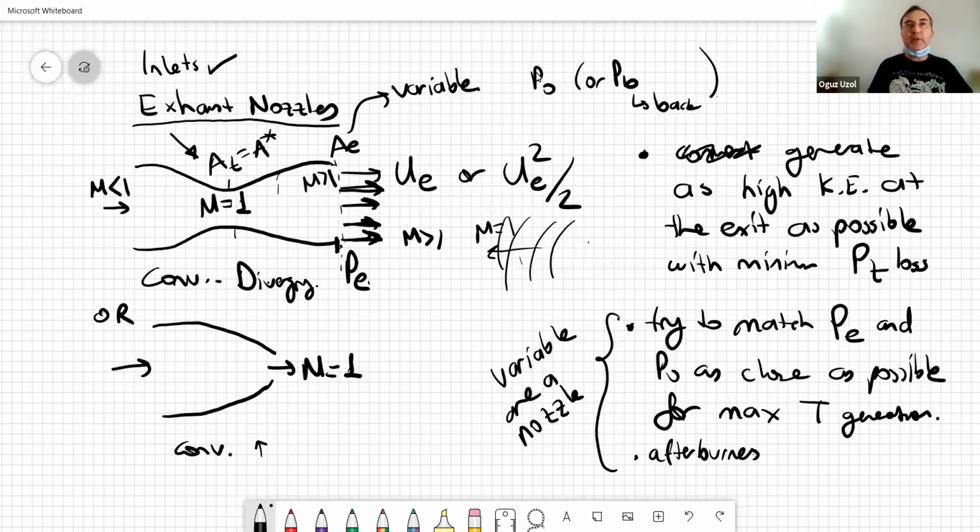In conventional aircraft, thrust is used only to overcome drag. It has nothing to do with lift, right? Normally, under cruise condition, thrust must be equal to drag. T must be equal to D. So the drag is actually normally much lower force compared to lift, much smaller compared to lift. So thrust is not very high during cruise flight. It just has to be equal to the amount of drag, so that in that flight direction you can maintain constant velocity, no acceleration flight, because net force is zero. Thrust is equal to drag.